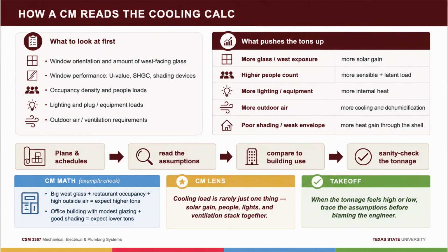Add the buckets, right about 54,800 BTUs per hour. Divide by 12,000, 4.6 tons. You'd talk to the engineer about a nominal 5-ton unit and let the selection work settle it. Sanity check with the rule of thumb. 2,400 square feet divided by 4.6 tons is roughly 520 square feet per ton, a bit lighter than the 300 to 400 office range, which fits. It's a small suite, modest occupancy, LED lighting. The rule of thumb and the calculation are shaking hands, and that handshake is what checking an estimate feels like.